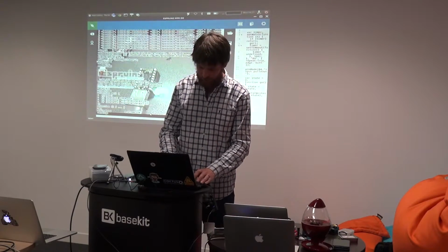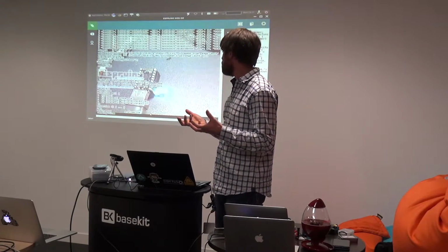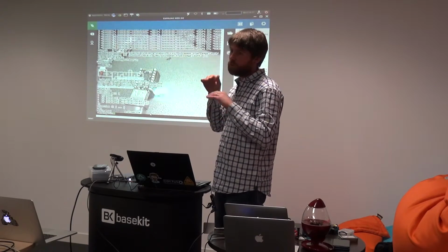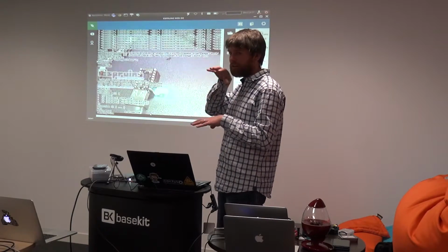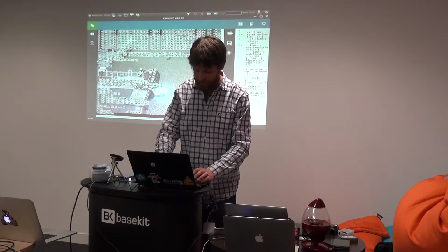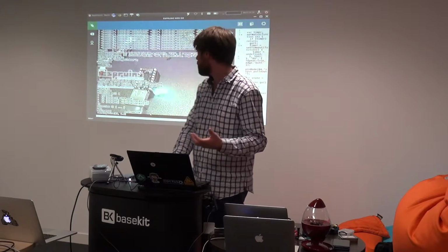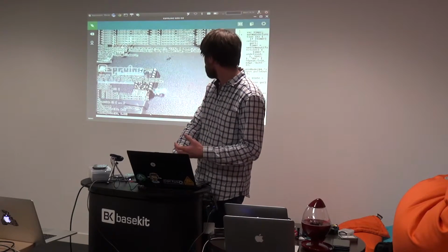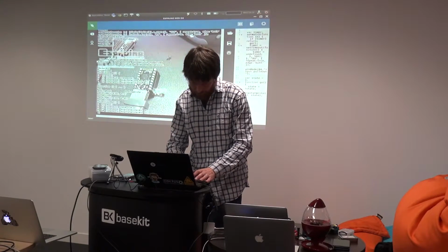One of the things we can do with this is we can create a pulse width modulated output. So this is basically, the outputs on this board can only give you 0 or 3.3 volts. So if you want to have something that's lit slightly dimly, you can maybe turn the output on for 10% of the time. So there's this thing called analog write, and if I just set it to 0.1, that would be 10%, and hopefully you'll see it's still on, but it's quite dim. You can dim it down a bit more. So we can actually just go back up, and we can put this in for a few different values.